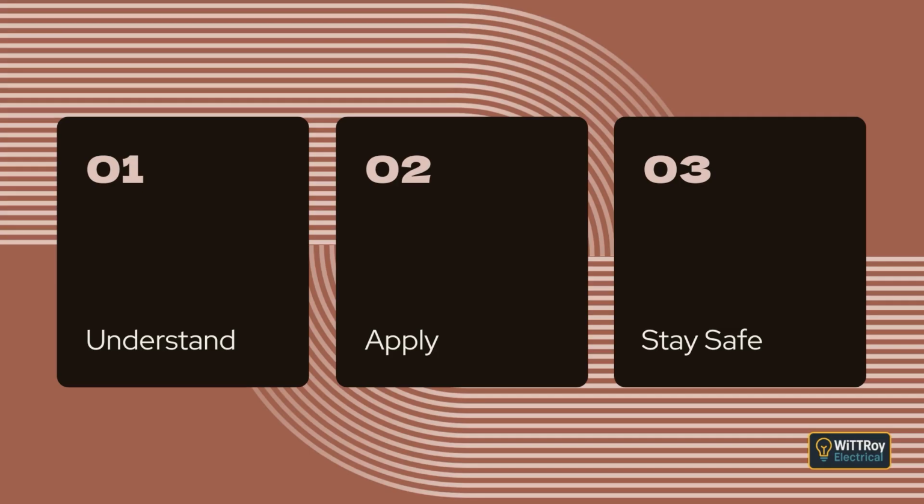Any installation method that is used must take into account external influences that may affect the wiring system. Clause 3.9.2 Methods of installation. This clause explains that many acceptable wiring methods exist, and examples are listed in Table 3.1. Other methods may be used as long as they meet the general requirements of this section and take external influences into account. If a relevant product standard applies to a wiring system, that product standard takes priority over this clause.